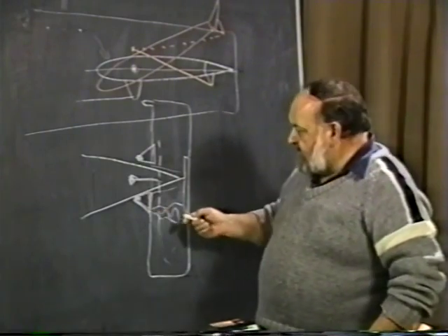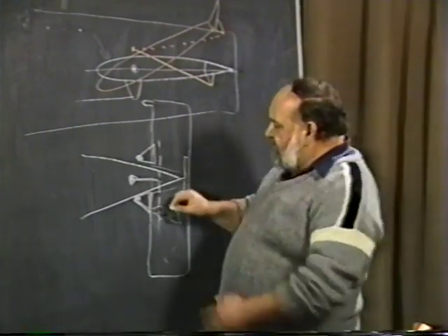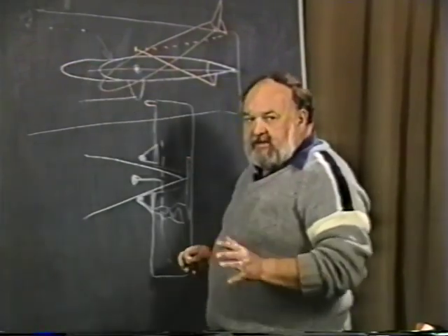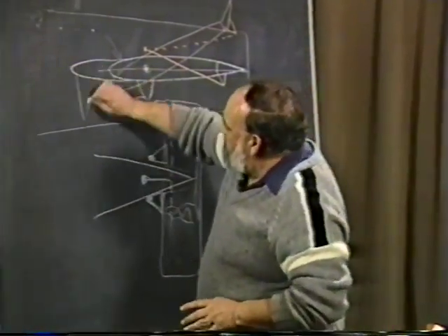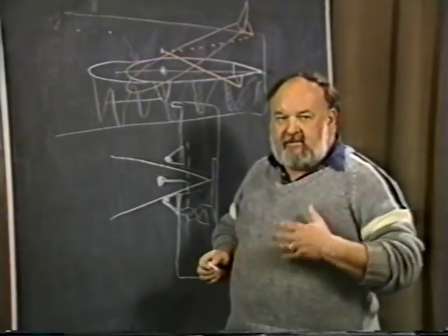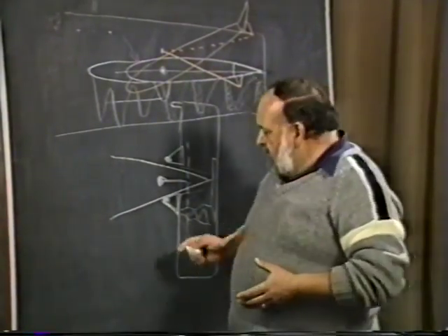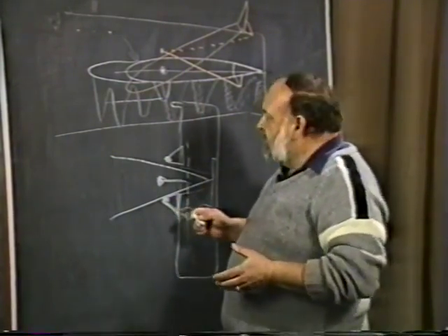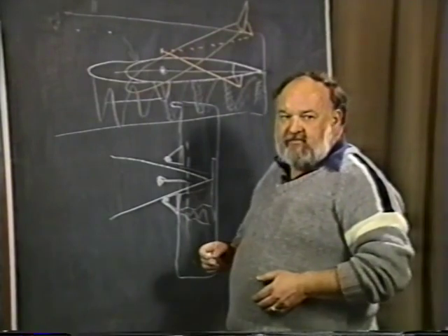aerodynamic vortex to it, and then even from a side view, when you have this extended surface sticking out in here, from a stability standpoint in spin, this area up against the side of the fuselage is a very powerful area to giving you spin stability. So by doing this one aspect of the thing, we had 3 or 4 things that helped us out on it. It's a good method and a good effective way of doing it.